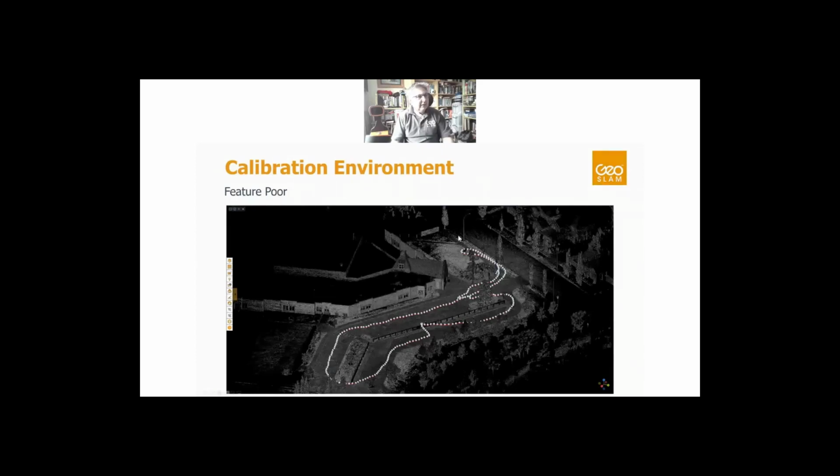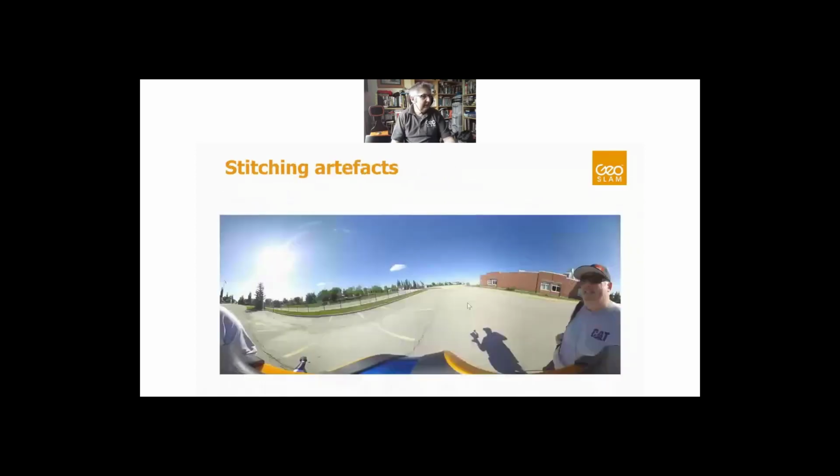So we have street lights here we could have used if they'd walked up and then come back. But unfortunately, it didn't quite make it that far. And again, there was lots of movements and jerkiness in the camera. Just didn't really give us the best possible calibration that we could for the environment. You can see in this image, it's quite open. You can see an effect of moving the scanner around quite a lot. You start to see these kind of stitching errors, and that's purely down to how we're taking and calibrating the data.